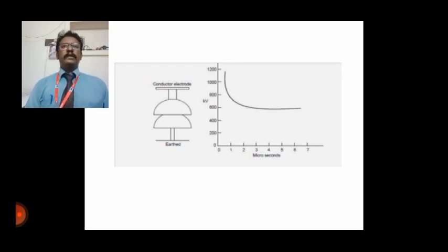breakdown voltage is not less than 30%, which is a nominal value, below which the voltage withstand level of the equipments to be protected. This has to be emphasized. So even though the rod gap is the cheapest one, it suffers from major disadvantages. That is, it does not satisfy one of the basic requirements of lightning arresters actually listed in that list. It does not interrupt the power frequency follow current.